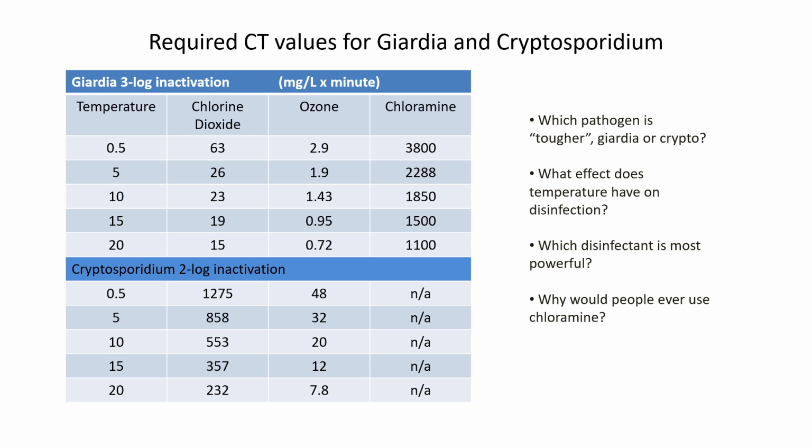So this assumes that there is to some extent just an exchange between the two, contact time and concentration, but the product of the two would need to reach this overall dose in order to achieve 3 log inactivation.